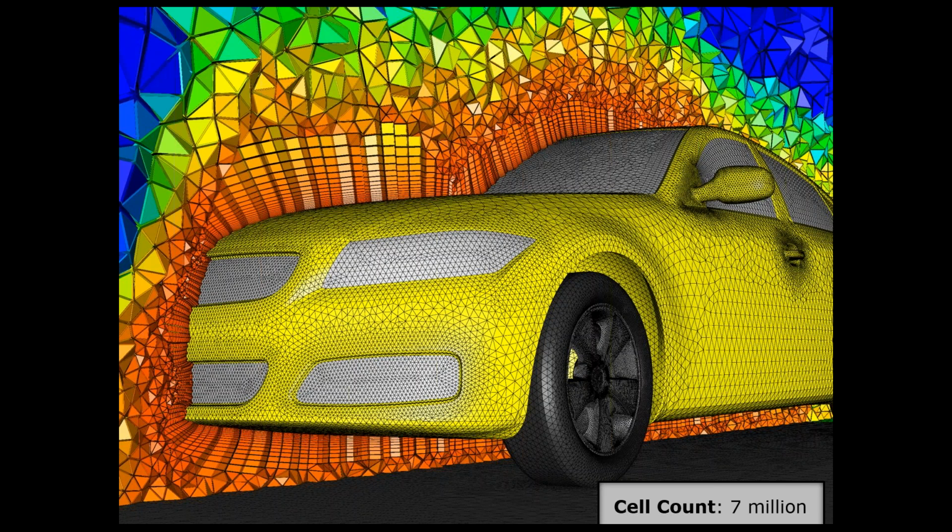We know that it's not exactly steady state, that wake is kind of whipping back and forth. However, it did converge to a quasi-steady state, and we averaged the drag over the last 1,000 iterations, and we were about 3% off the experimental coefficient of drag. So for this baseline mesh and this proof of concept study, we're on track. We were doing a pretty good job.